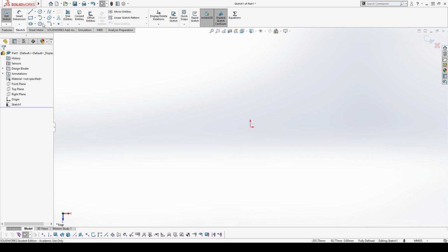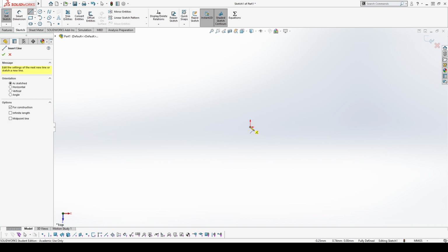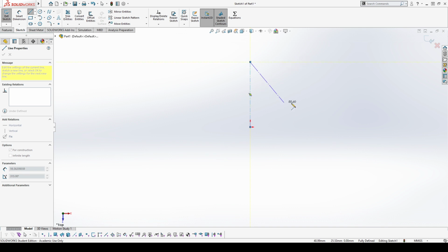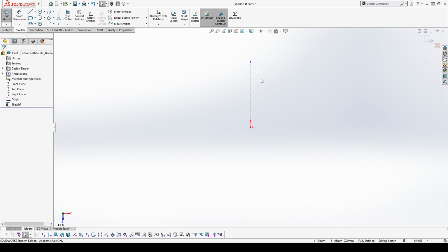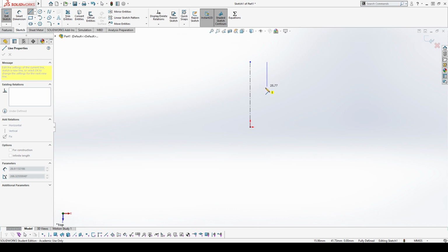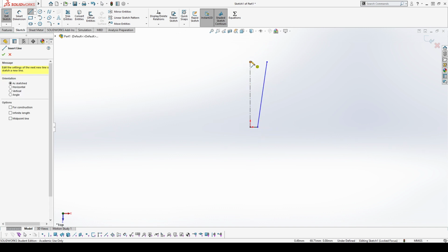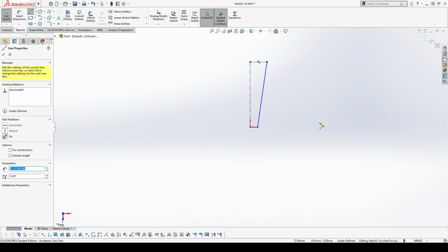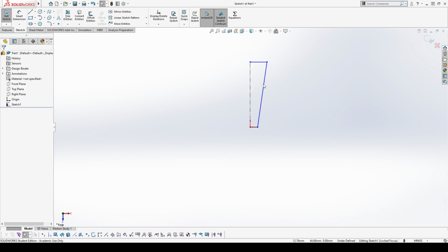It's nothing more, nothing less, but it's very helpful sometimes to start with a center line, and then, if I'm drawing in other lines, like again for that cup, if I want to make a cup, I can draw in that, and then add in another line up here. So now I have my center line that everything's going to revolve around, and then I have the outside edge of my cup here. So that's kind of useful. You can also just use it to automatically add in a bunch of construction geometry if you're sketching stuff out and building stuff in there that isn't actually there.